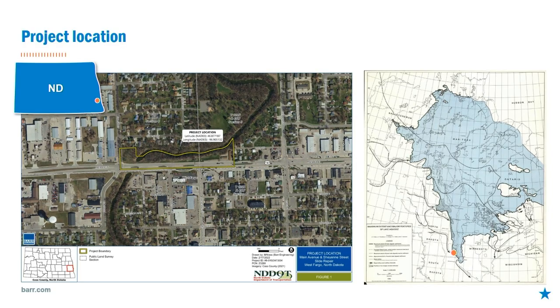Those clay particles are very soft glacial lacustrine clays. That means they're very compressible, they're highly plastic, and they have low shear strengths, which creates a lot of landsliding issues. So we actually have a lot of landsliding problems in the eastern part of the state, in the Red River Valley, and most of those are at river locations, specifically the outside bends of the rivers. You can see the Cheyenne River snaking through the picture on the left here. As the river goes from east to north on the right edge of the yellow box, that's the outside bend, creating some erosion issues and causing some instability in our embankment and the riverbank.